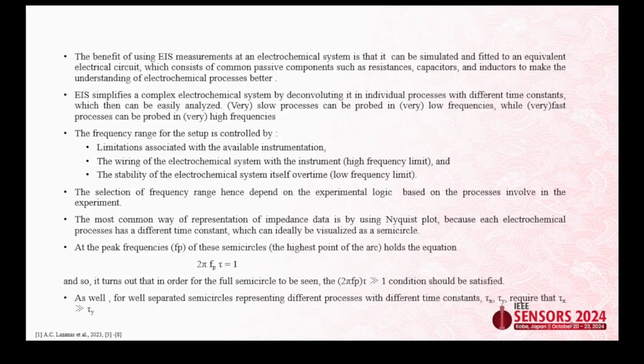To start with, you either compensate for the capacitance or the resistance of the wires that you use to take the measurement, or always try to keep those things constant while taking the measurement, so that they do not affect it. While taking a low frequency measurement, the probes or the wiring of the electrochemical system is very important. Try to use triaxial cable as compared to other cables.